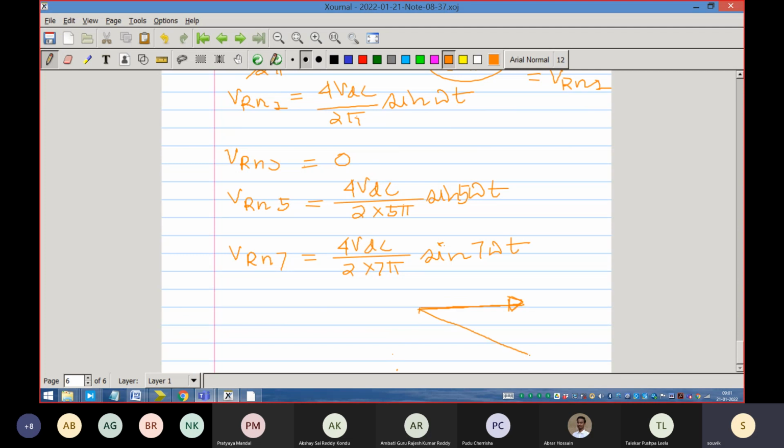This is the flux, and this is the current. Now which flux and which current? Because the machine terminal voltage has harmonics. So which flux and which current? Therefore the torques are produced between fundamental voltage and fundamental current.